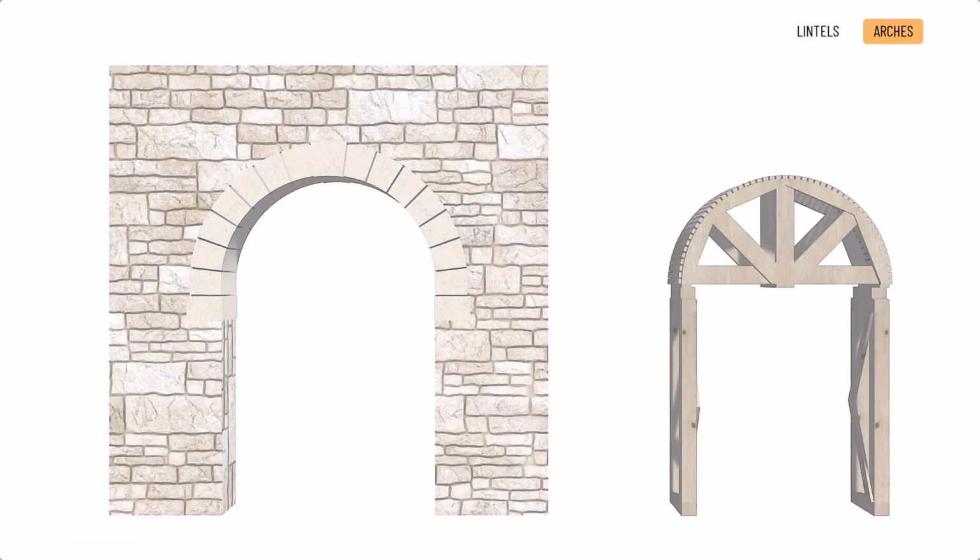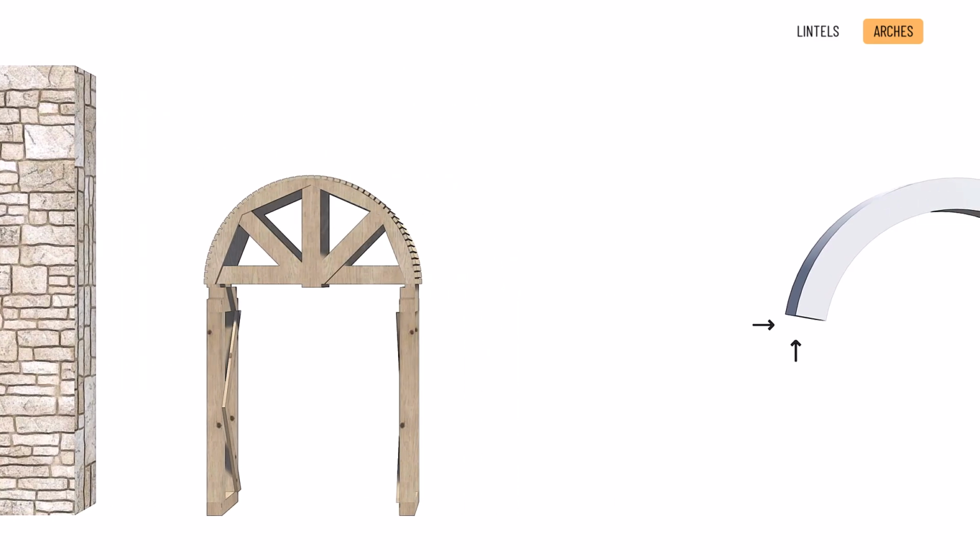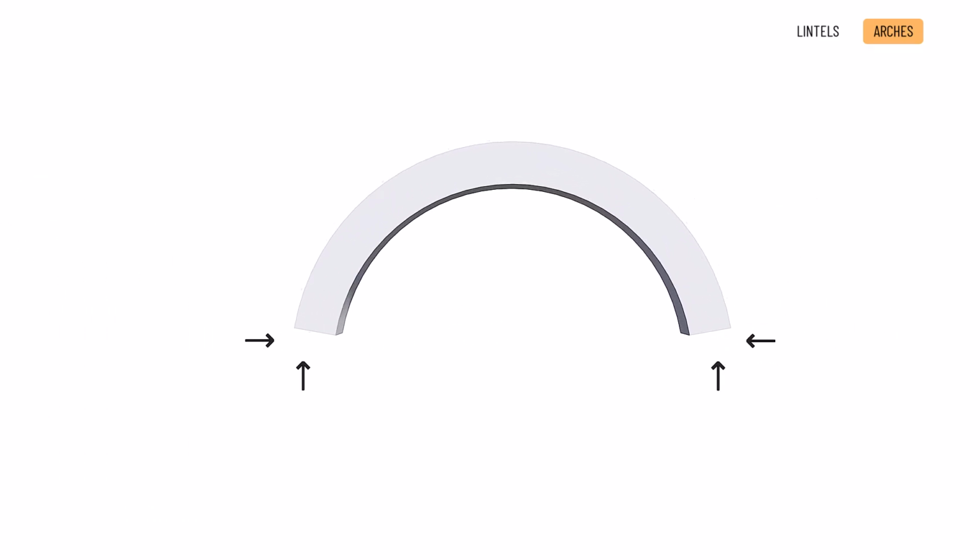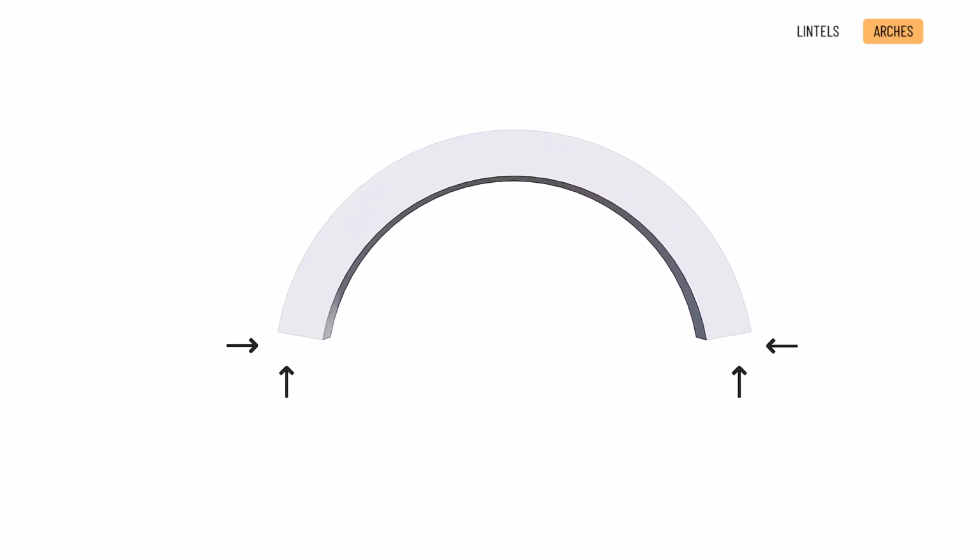Arches. Curved spanning structures of openings. Arches are a special form of lintel originally constructed of stone or brick, using a wooden template to support the structure. Over the centuries, different forms of arches have evolved. What they all have in common is that they are subjected to a curved, compressive force at the supports, resulting in horizontal force components in addition to the vertical ones at the supports.